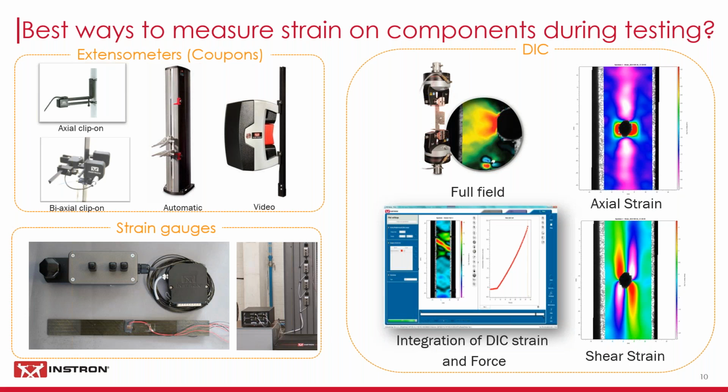It's something that we can readily connect to our systems. And in fact, multiple strain gauges can be connected, as you see. There's a single adapter in the photograph, and then a multi-channel add-on to our system, so we could support up to 11 strain gauges on the typical electromechanical testing machine.